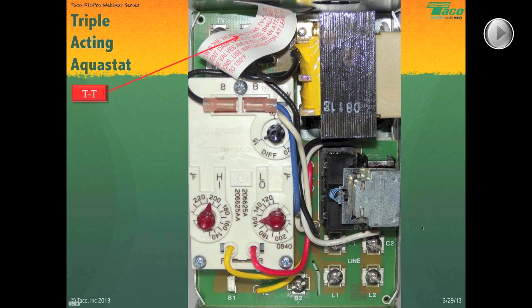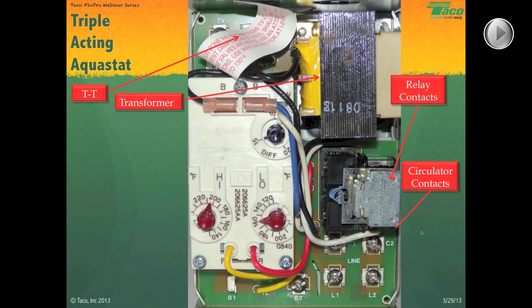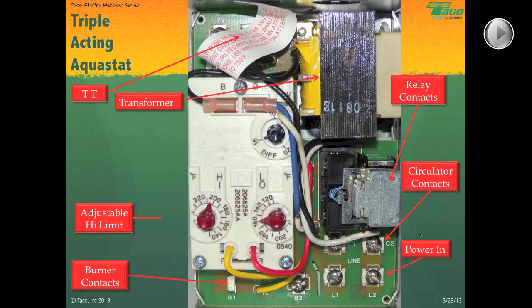Behind that little tag up top, you have your TT terminals for your thermostat. There's your onboard transformer. The relay contacts are over there on the right-hand side. C1 and C2 down below the relay contacts. L1, L2, that's your power in, your line voltage in. Right next to that, on either side of the yellow wire, you have B1 and B2. Those are your burner contacts. And so far, it's pretty much the same. The difference is going to be in the next three items.